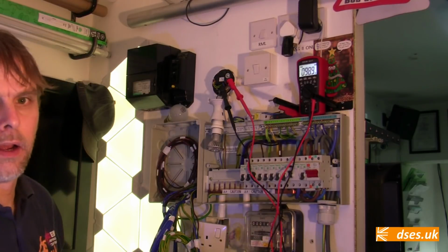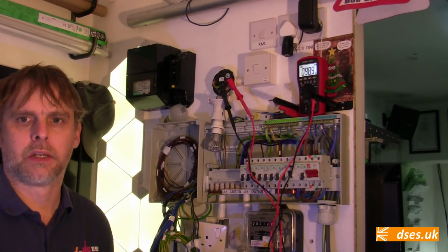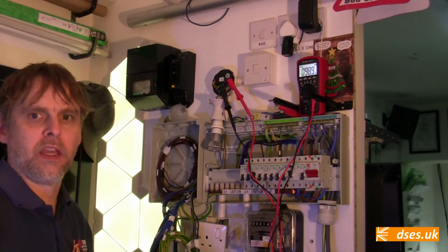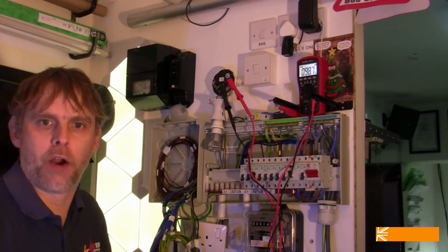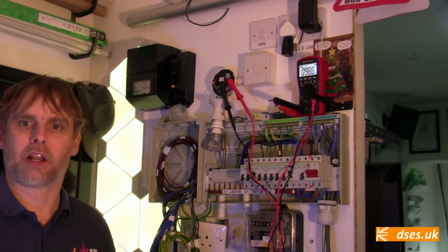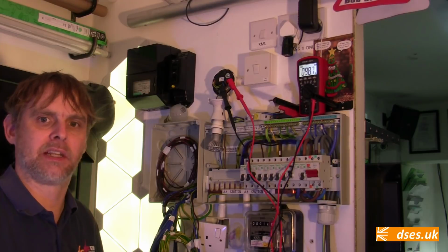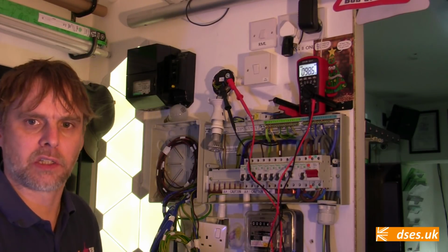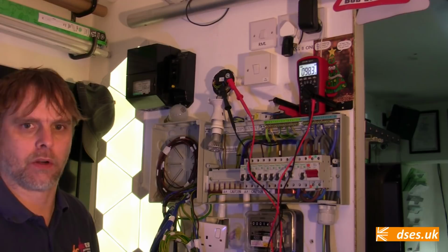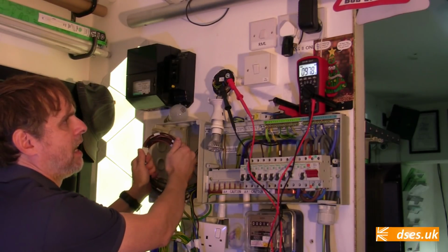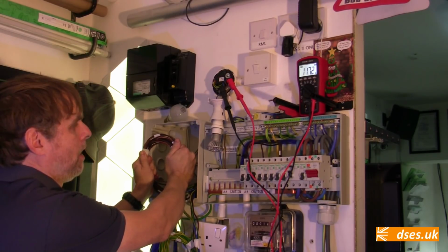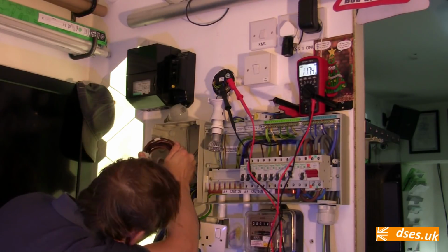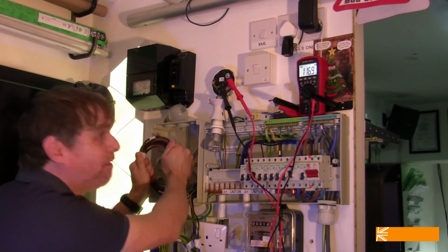Okay. Now, if this is down to capacitance, then I should be able to improve the, albeit unwanted, performance of my wire capacitor by squeezing the wiring, as that will reduce the dielectric insulator by closing the air gap and pinching together the plastic insulation of the two wires, thus reducing the size of the electric field the current has to cross. So if I squeeze that now, we should see our voltage. Yes, look at that, it's gone up to 115, 116 volts. So I'm improving the operation of the capacitor, and I can actually see the light is starting to light again even with the voltmeter connected.